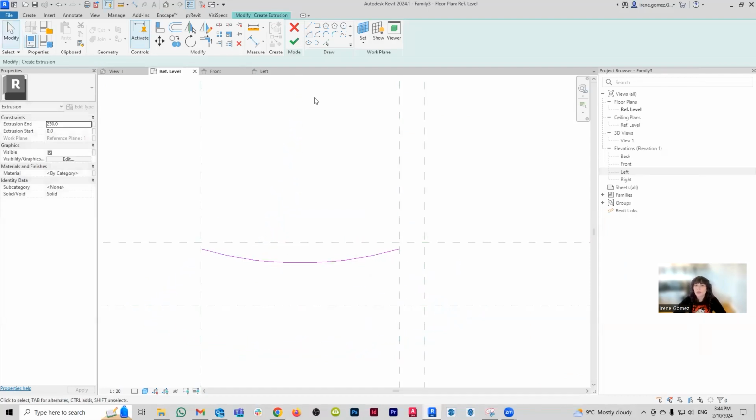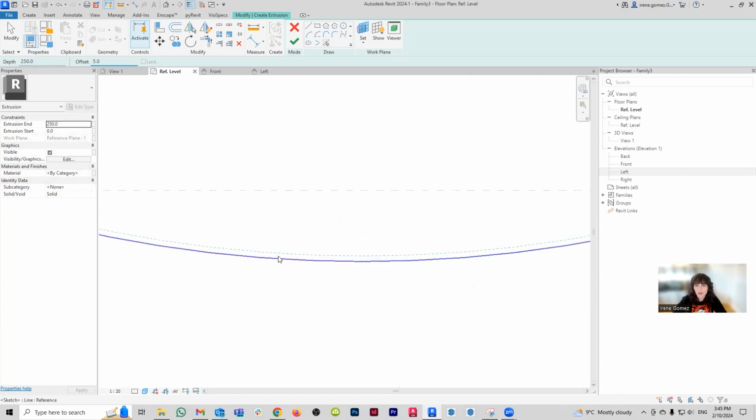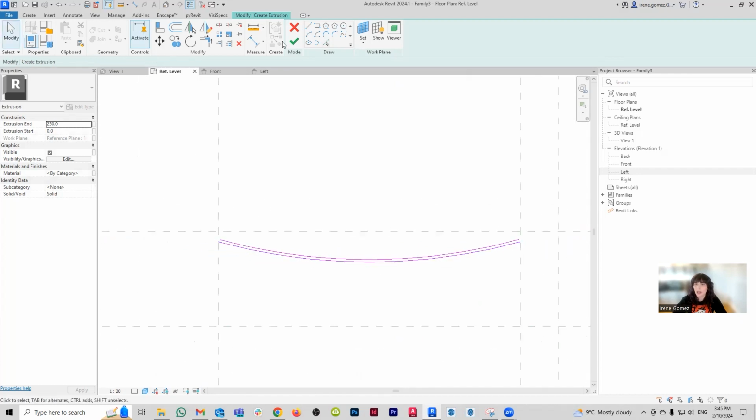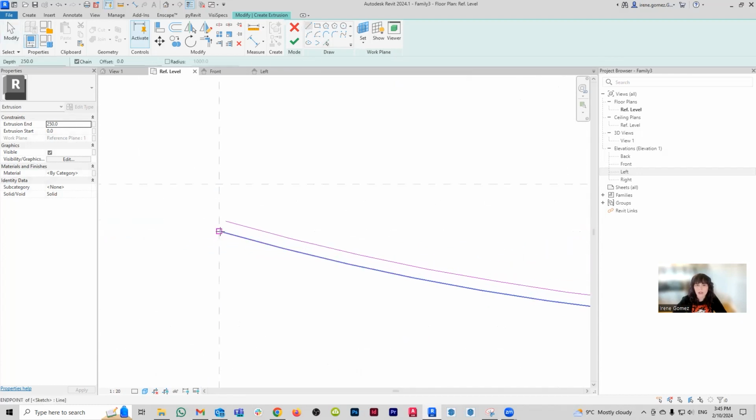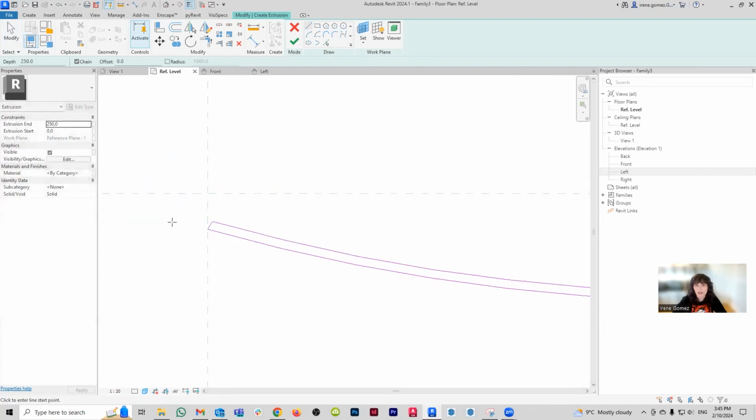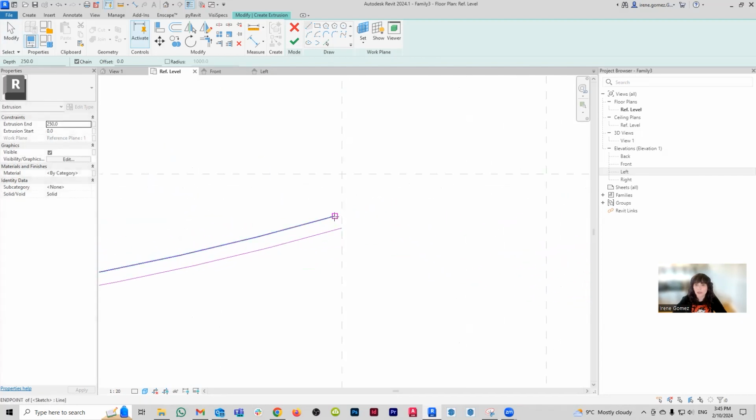Okay. So with that, now I'm going to use the thick line option, and I'm going to give it an offset of like 5 millimeters for thickness. So I can basically create kind of like a metal sheet. 5 millimeters might be a lot of thickness, but it's fine. Okay, so we're going to close our boundary and close it here on the other side.